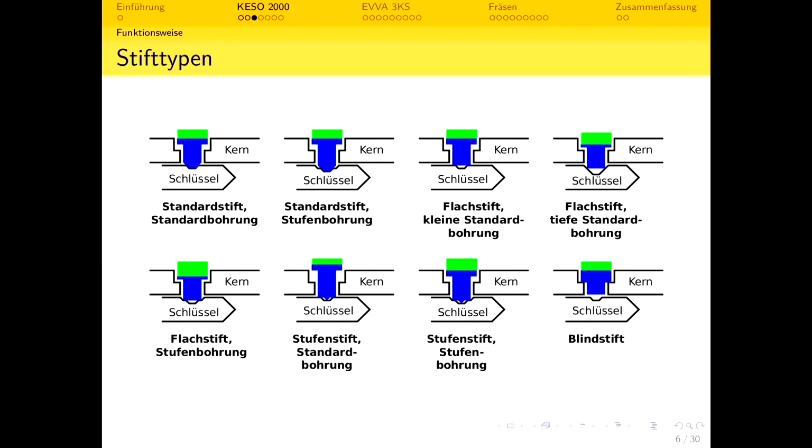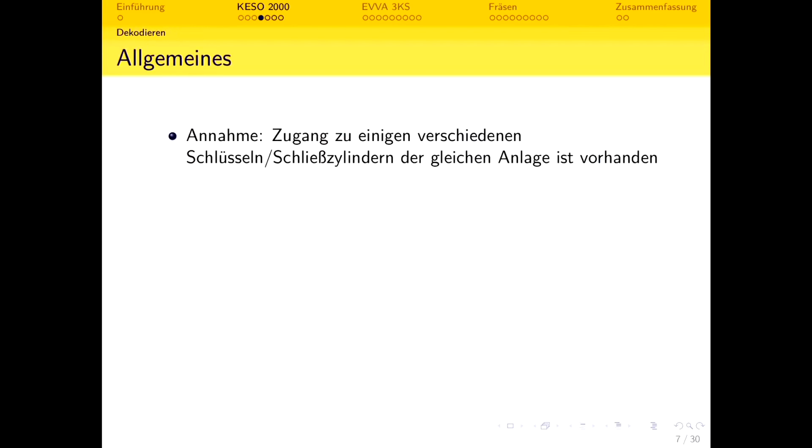In many cases, we also, for houses where different keys have to fit the house door, for example, not all of the drill holes are actually used. There may be a blind pin, and independent of which key is inserted into the lock, that pin doesn't affect the lock operation, in order to have the same core of the lock and have different keys able to access it.